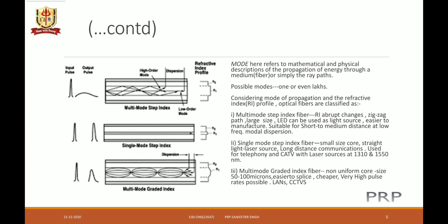Secondly, the single mode step index fiber. Here the core size is very small, of the order 2 to 15 micrometer. In general it could be near about 8 to 10 micrometer, and the light injected into it is from a laser source. It requires a laser source because the core is of a very small size, and hence very focused light has to be injected in order to make it travel straight to the center of the core axis.